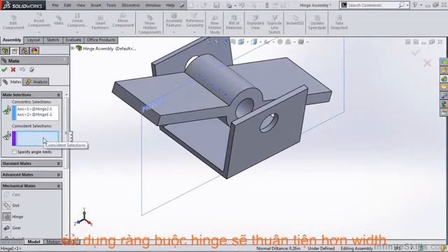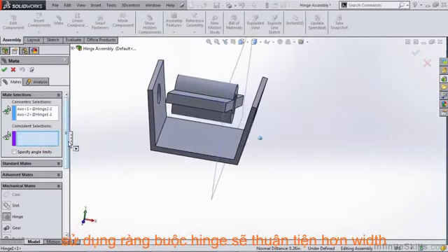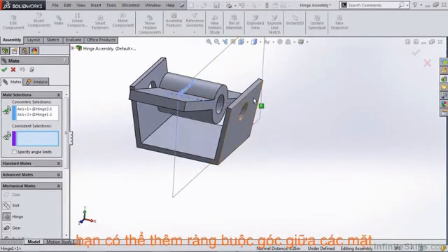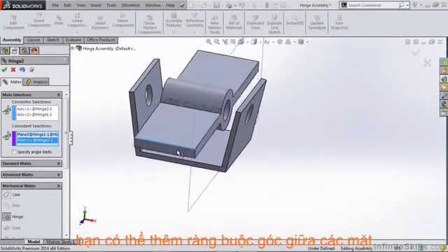The next thing it needs is a coincident relationship. Now in this case, it's not a full mechanical assembly, so there are no touching parts. So I have a plane that's located in my outside bracket piece that allows me to create this mate. So simply selecting plane 3 and then the side of our face creates all the mates needed to rotate this part.